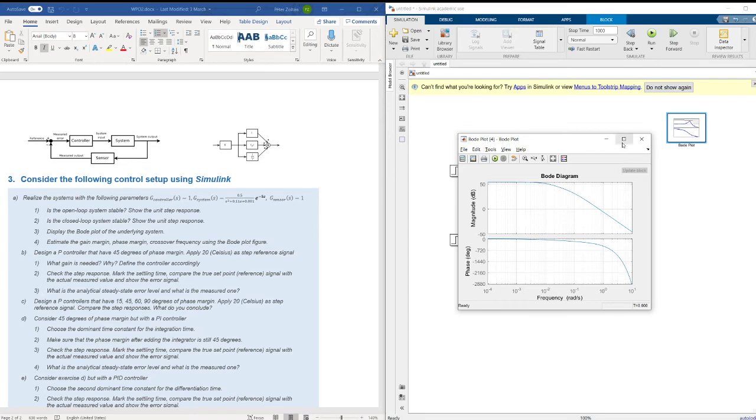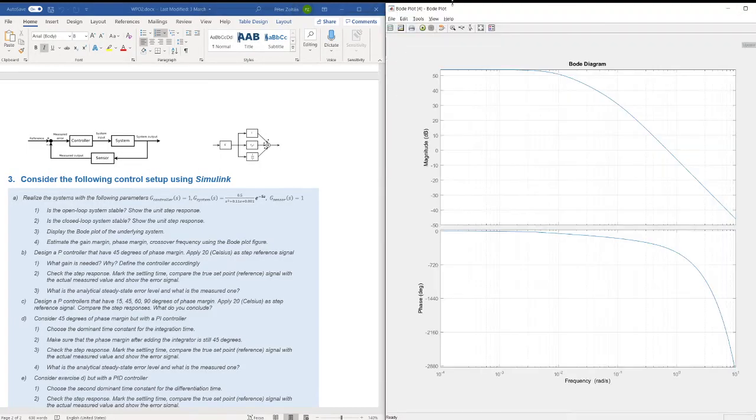So as in the test, you should be able to read all the parameters. Now, I am going to read only some basics. So we see that the static gain is here, and we check what is now the phase margin. So for the phase margin, we have to look for the crossover frequency. So where your magnitude graph crosses the 0 decibel. I am using the mouse, and I am more or less here at 0. I am looking, yeah. So it's quite close. You can see here the magnitude value and the frequency is 0.7 rad per sec.